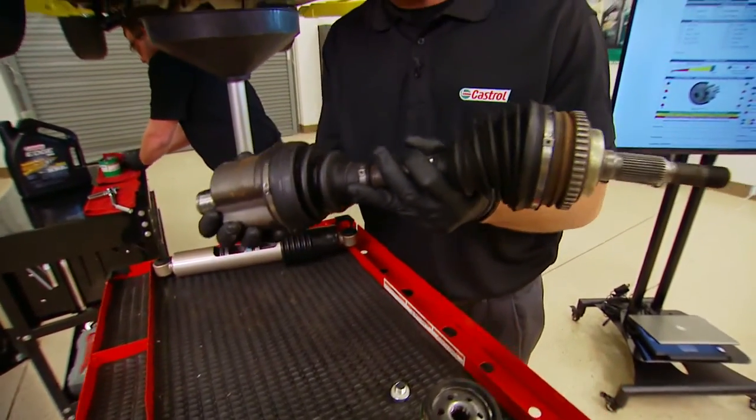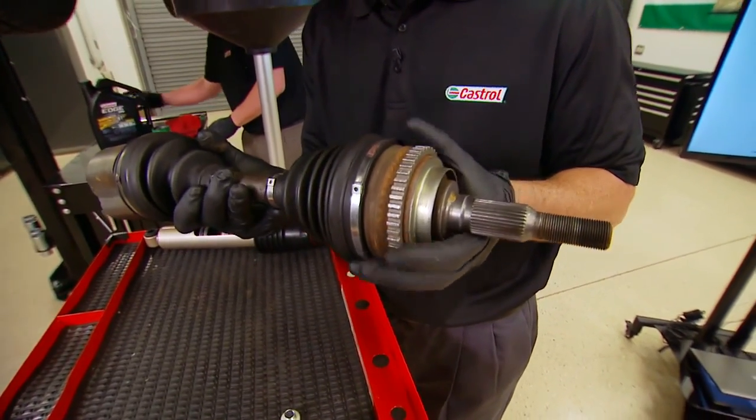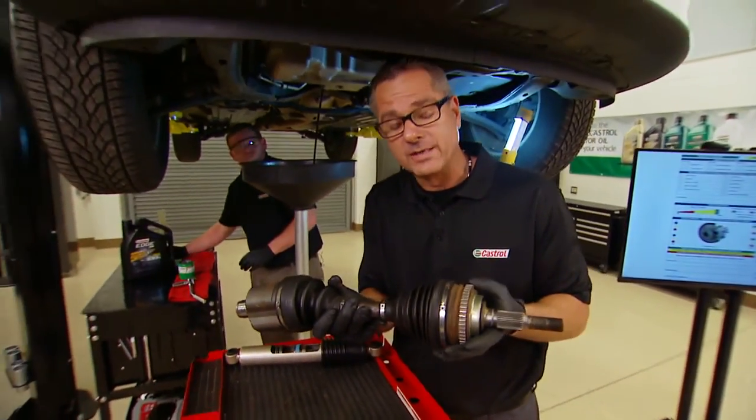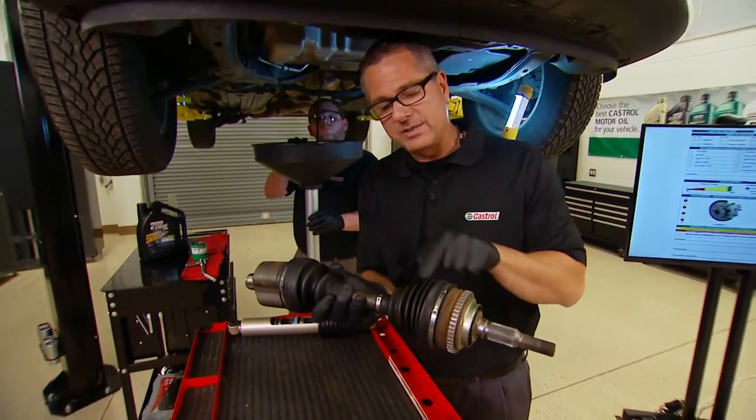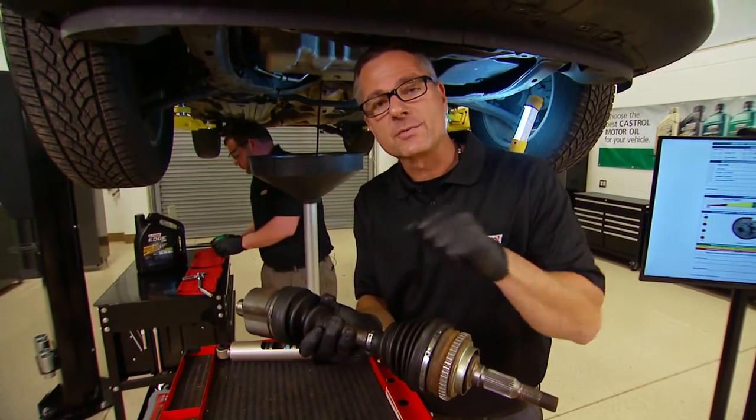There's also constant velocity joints. Now, constant velocity joints have a plunge joint on one side and a fixed joint on the other. But this thing's rotating with engine speed, no matter how fast the car is going. Now, you also have these boots. These boots could tear, grease could come out of that. Now, a classic symptom of that, car may turn to the right or left and click.